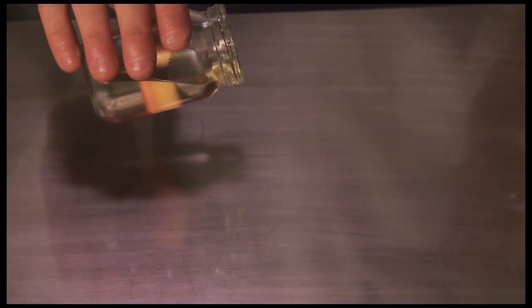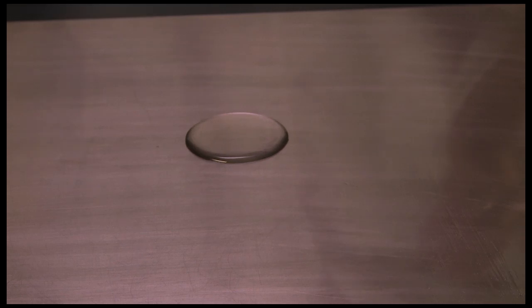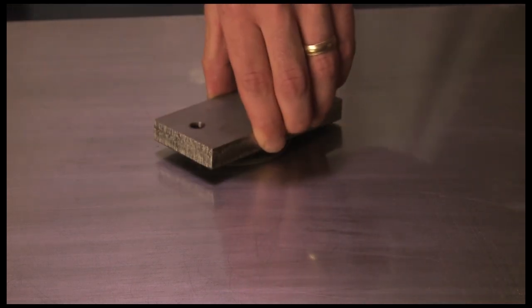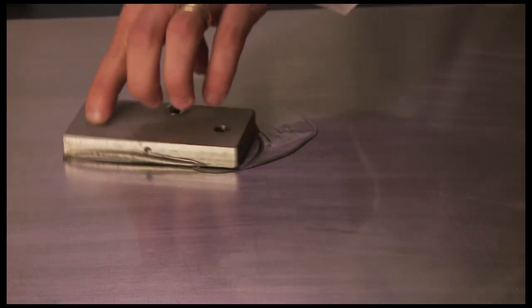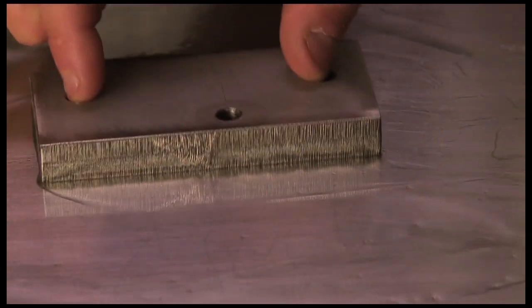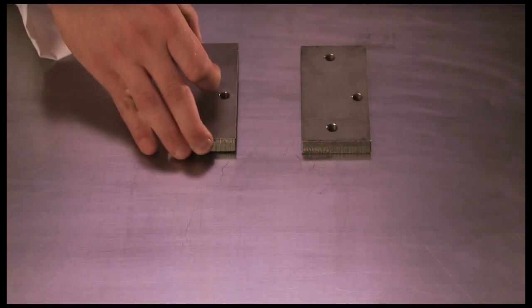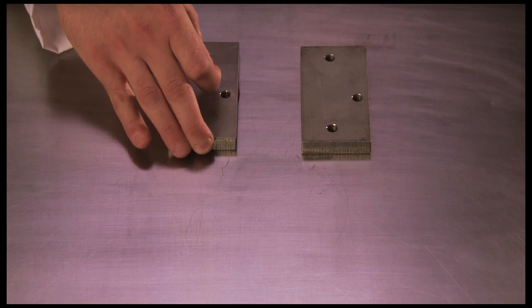When oil is added between the two pieces of metal, you can see that less force is needed to move the block, and there is less resistance. The oil has created a barrier between the wear points of the metal, reducing the friction. Very little wear is occurring, and very little heat is being generated. It also requires less force or amperage draw to move.